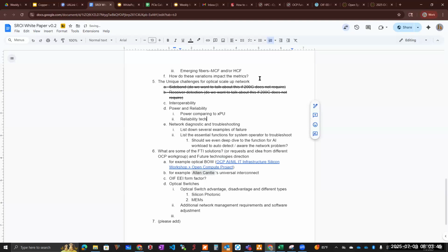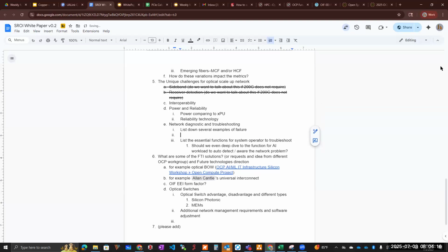Yeah, Bobby, I could say a little bit about the network diagnostic section you've got there. This is related to the hyperscaler's request that if something goes wrong, they can pinpoint where the problem is. One of the complaints I've had is that if you use a non-retimed module, there are typically no diagnostics in it, so you can't tell which end of the link needs to be replaced. I believe that's really what this section is meant to be talking about: how do you deal with that if you're trying to achieve lower power?